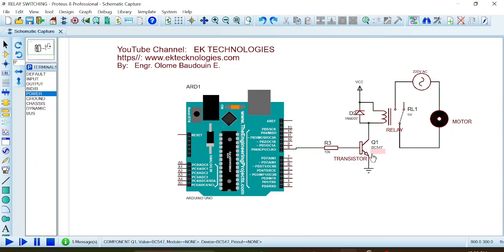Now, in order to control this circuit to switch, I would like to use an input pin to activate the relay. Here we use the push button. I've already shown you how you can connect a push button to use it in such a circuit. That push button as well can be used in resetting the microcontroller, as you see here. So we have the pull-up resistor, and here is the push button. When you actuate this push button, it will reset the microcontroller to start back the process.